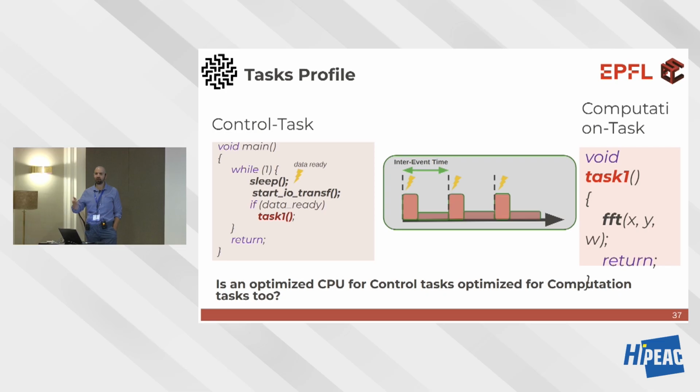So you will select an ISA among the ones that we saw yesterday, different between the two. Good. So you will select, for example, the vector extensions on the core running the FFT. Probably needs a double floating point. Another extension could be the double precision floating point RISC-V extensions on the FFT CPU.